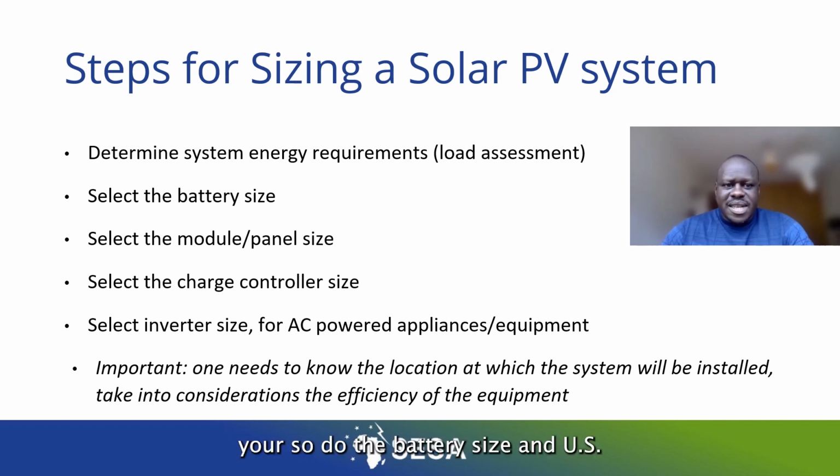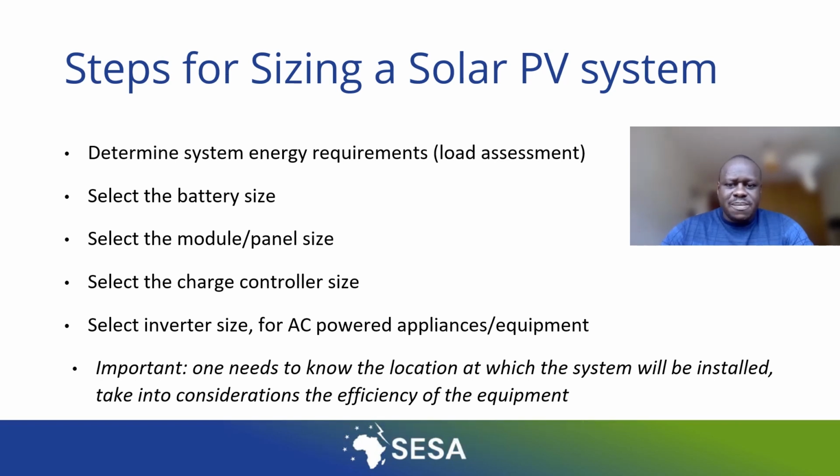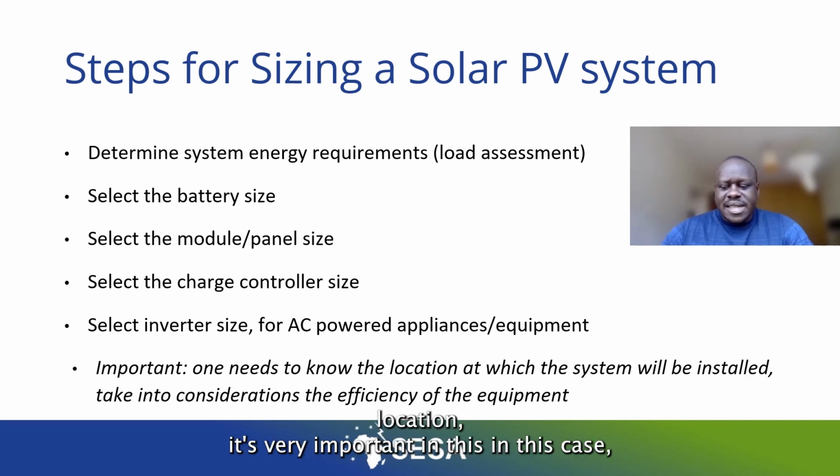You also do the battery size, you select the charge controller, and you design for the inverter. As I explained in the previous video, in order to determine the size, you also need to know where you are going to install this system. So the number of sun hours in a particular location is very important in this case.